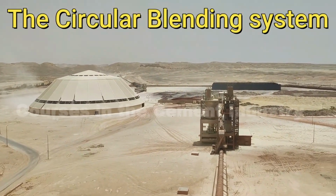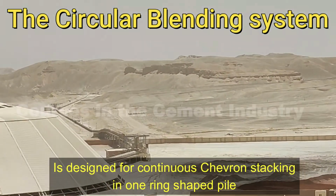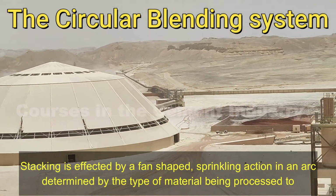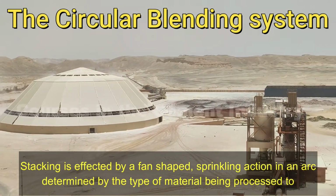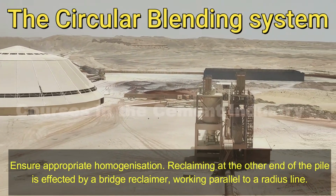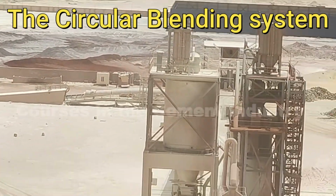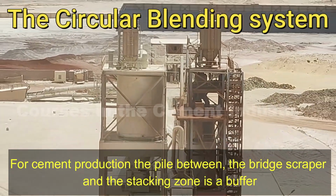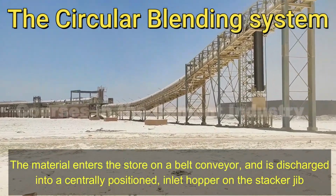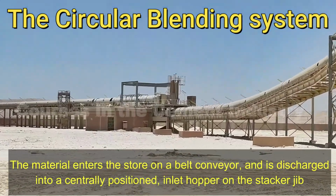The circular blending system is designed for continuous chevron stacking in one ring-shaped pile. Stacking is effected by a fan-shaped, sprinkling action in an arc determined by the type of material being processed to ensure appropriate homogenization. Reclaiming at the other end of the pile is effected by a bridge reclaimer, working parallel to a radius line. For cement production, the pile between the bridge scraper and the stacking zone is a buffer. The material enters the store on a belt conveyor, and is discharged into a centrally positioned inlet hopper on the stacker jib.